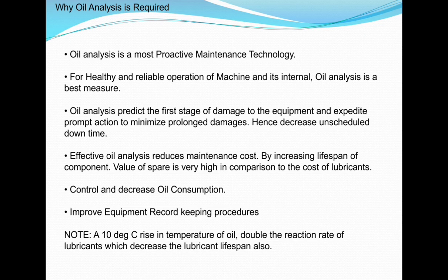The cost of oil is very small in comparison to the cost of the spare parts. If we analyze the oil in proper time and keep a record of that oil analysis, and accordingly take care of the machine parts, we can reduce the cost of spares, which is very high.